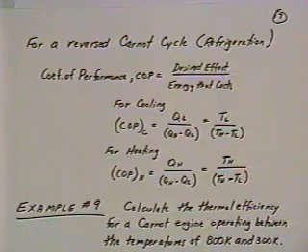If you're in a heating mode, then you're interested in the amount of heat that can be supplied, divided by the energy that it costs you to do that. You'd like to do that as efficiently as possible, and so the term used is coefficient of performance: the desired effect, either heating or cooling, divided by the energy that costs.